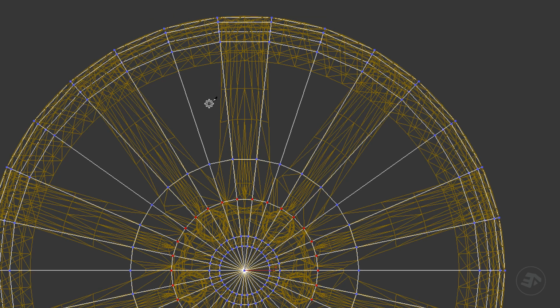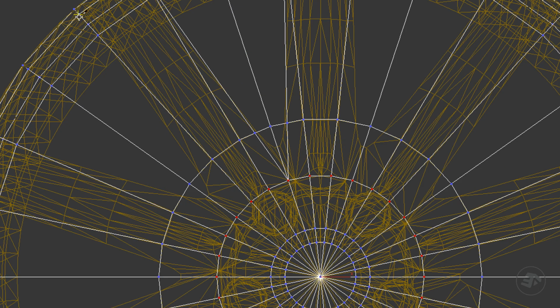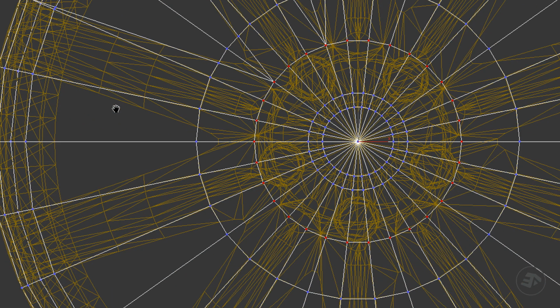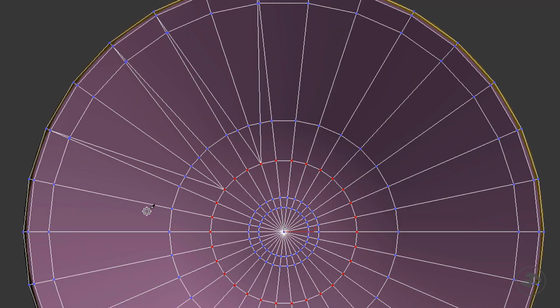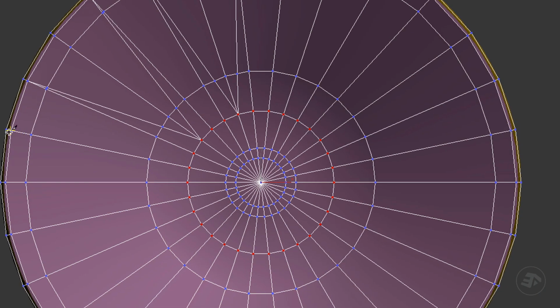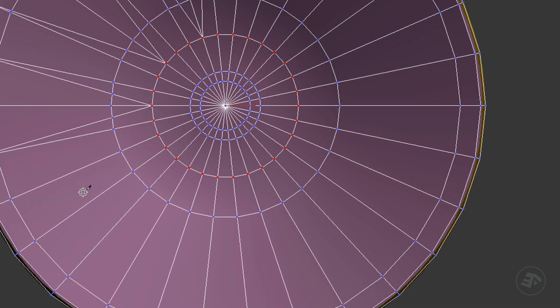Switch to vertices mode. Activate Snap to Vertex while using the Cut tool. If you are familiar with other designing packages, what we are doing now is creating a sketch of the reference rim that will become the foundation of our rim shape.